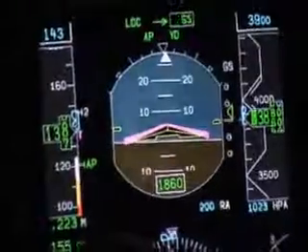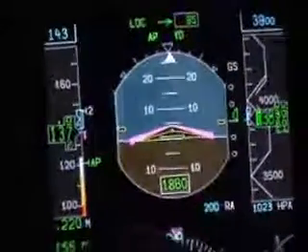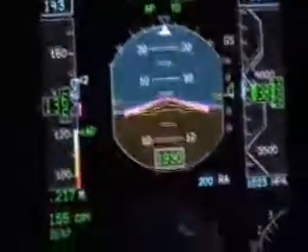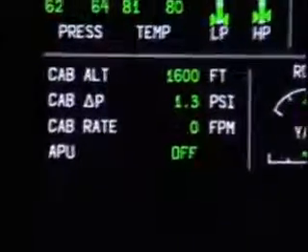During holding at any flight altitude, simply return the manual controller to around the 12 o'clock position to set null cabin rate, and then reset the desired cabin rate when descent is resumed.